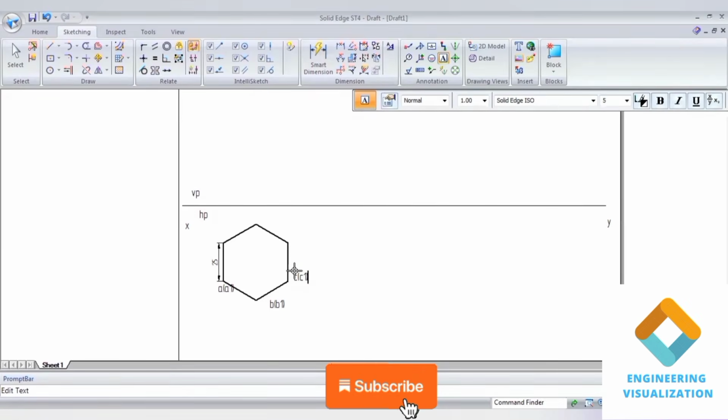Here we need to find the center of the hexagonal prism. For that, at least one or two lines need to be drawn, because since it is a prism, we don't need to draw all the lines to find the center of the axis. Inside this hexagon we should draw thin lines, not thick lines.